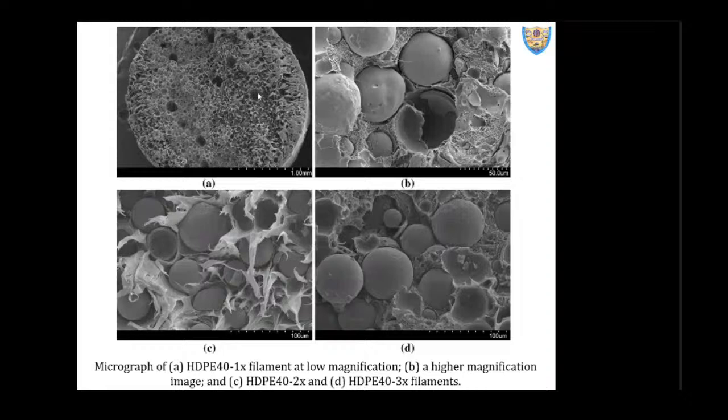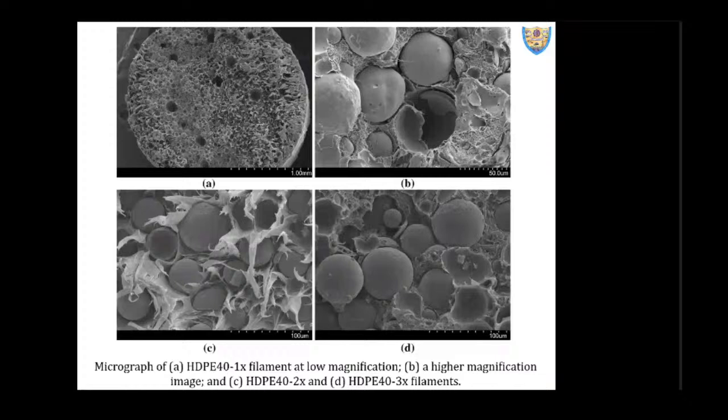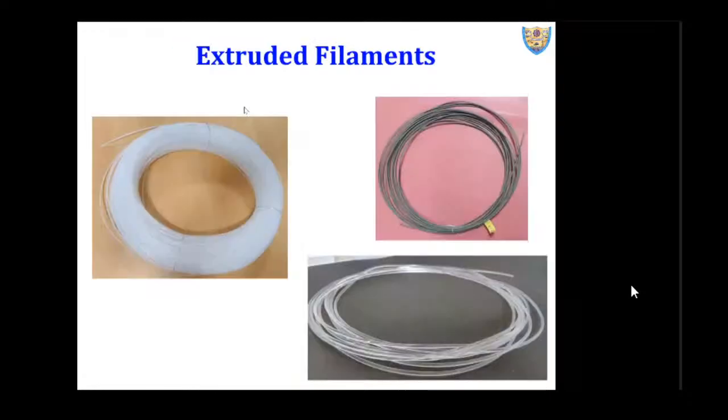them, you quantify them, and give the subsequent justification. Reviewers agree because they know it. And now, what is the reason for such air entrapment here? The reason is the machine which I have used. And what is that machine? I said it's a single screw extruder, right? This single screw extruder is a non-vented type.